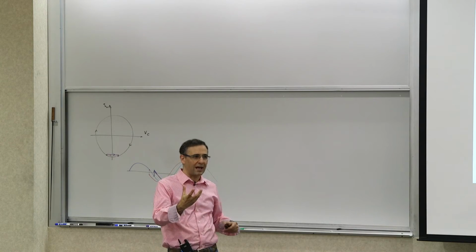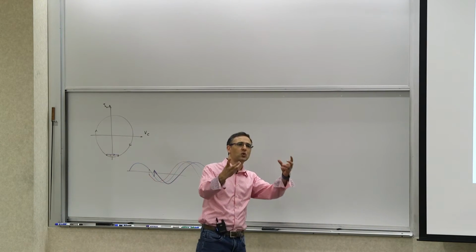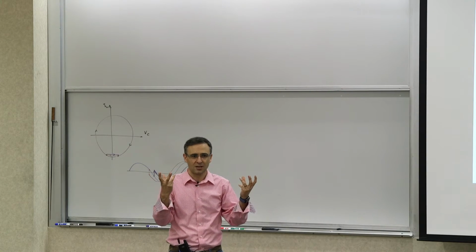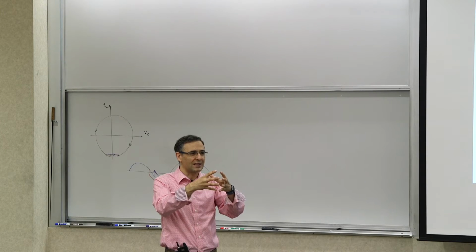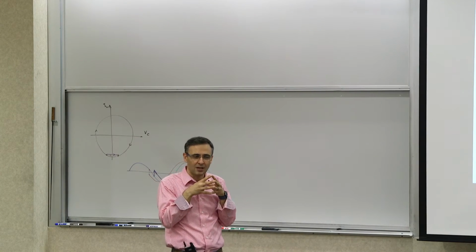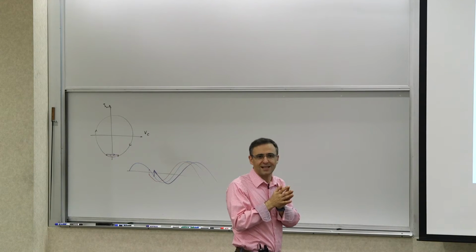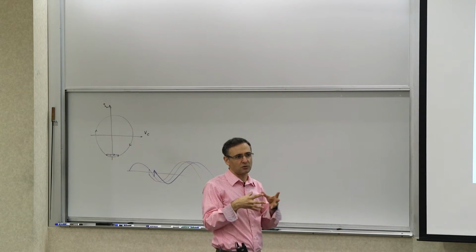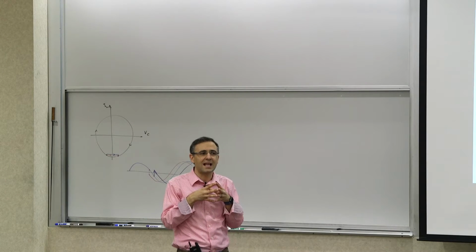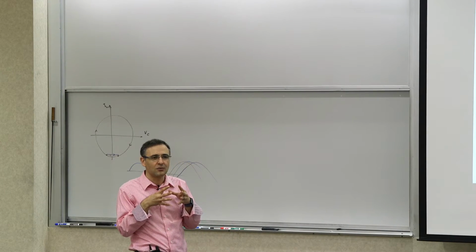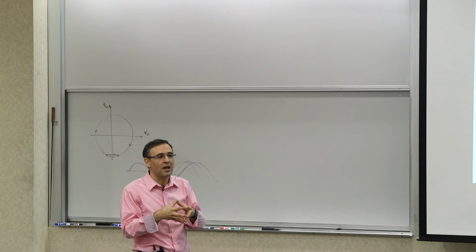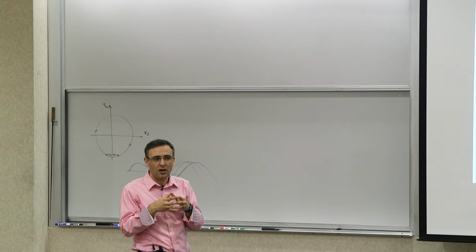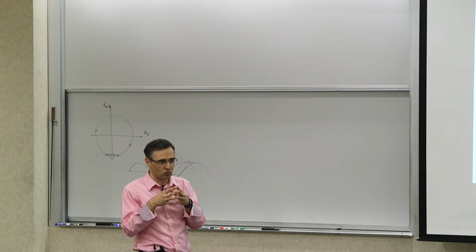One way to do that is to make two identical oscillators with the same component values, and make them node for node parallel, attaching every node to an equivalent node of the other one. They would both oscillate at the same frequency and in phase because they will lock to each other. But now you have increased your charge swing. You have increased your current by a factor of 2, and your signal power has gone up by 6 dB, because your charge or current swing has doubled.